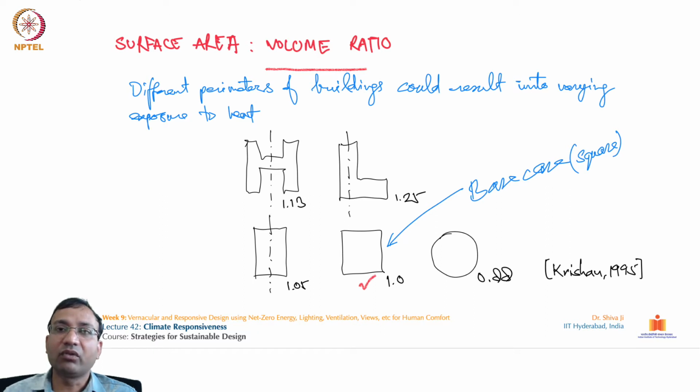So if you are living in colder places, then it is ideal for you to increase the surface area. But if you are not living in colder places, and you are rather living in very hot places, then it is always desirable and recommended to minimize the surface area, so that you reduce the heat gain in the building. In turn you will be spending little, or in a controlled manner, for cooling that space.